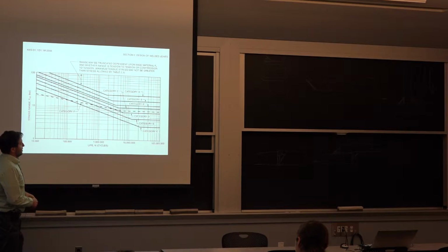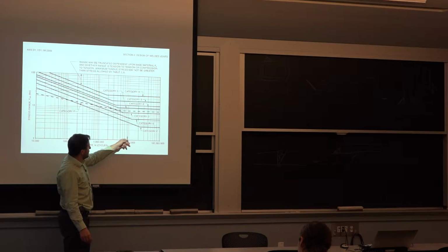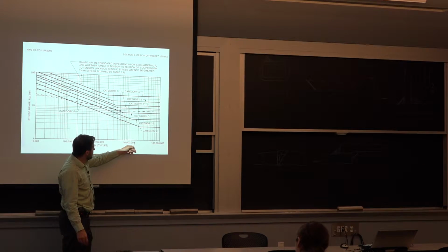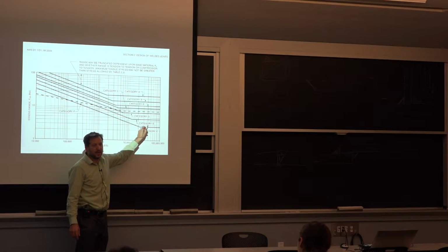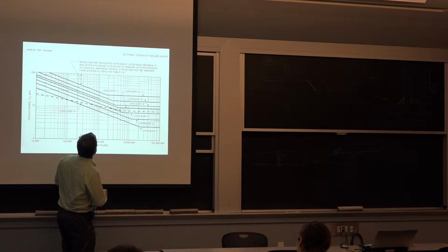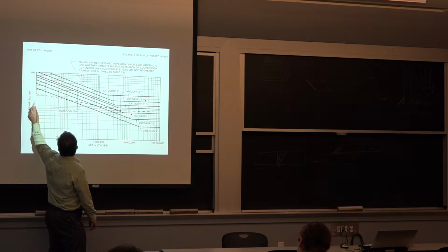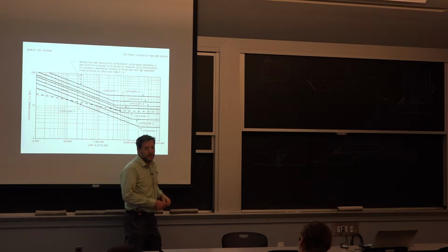So if we're thinking about something that will have a little bit of vibration, say we go all the way to 20 million cycles, when we pretty much have a constant value of stress that we can follow. So if you don't have weld on your structure, the code will say you can put about 23 KSI of stress in the material.